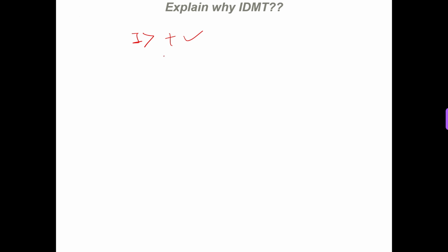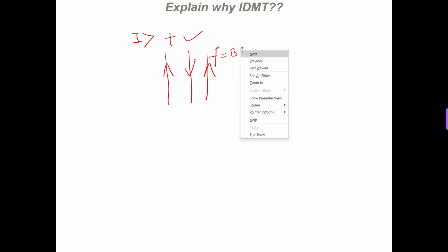Second is mechanical damage. Suppose we have parallel conductors like this, in any machine, in any power system. When a fault current comes, suppose in any direction, in one conductor and the second conductor, it can be like this, it can be like this in the same direction. For any flow of current, we know that there will be a force acting on these conductors, that is BIL.